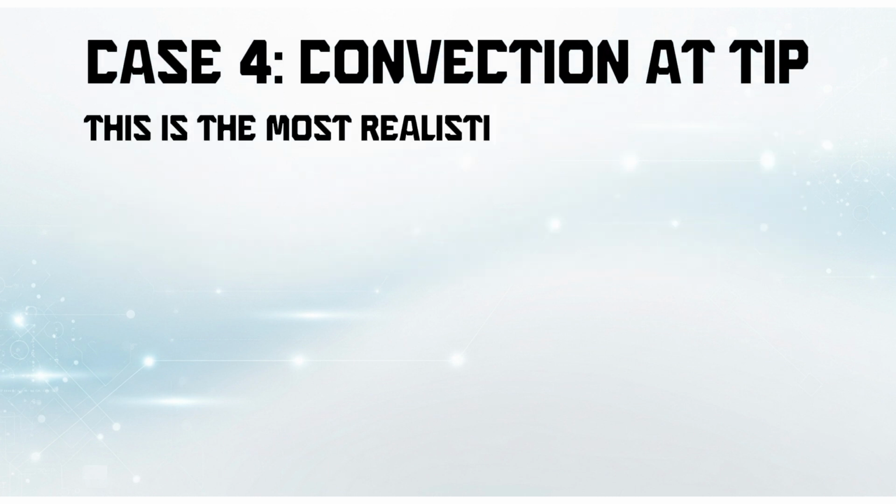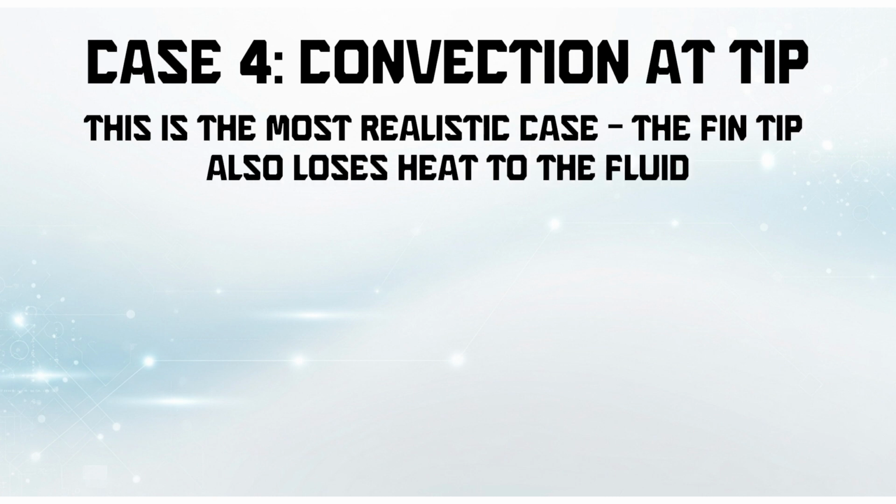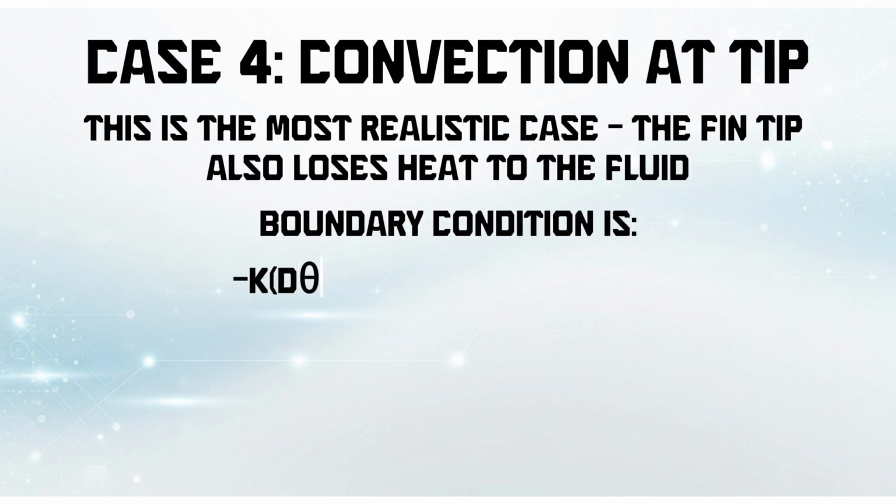Case 4, convection at tip. This is the most realistic case. The fin tip also loses heat to the fluid. The boundary condition is minus k times dθ/dx equals h times θ at the tip.